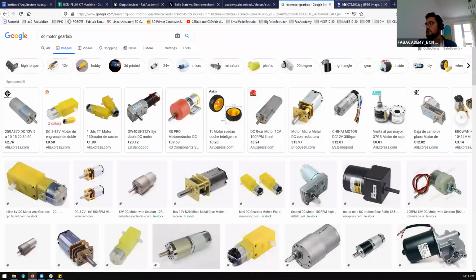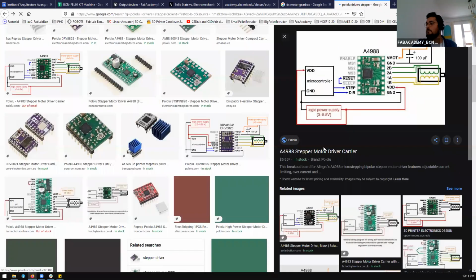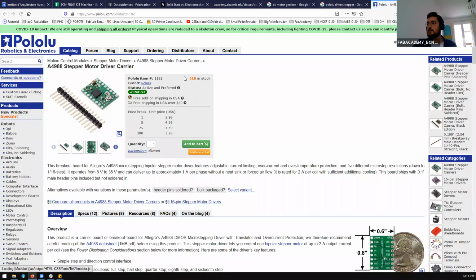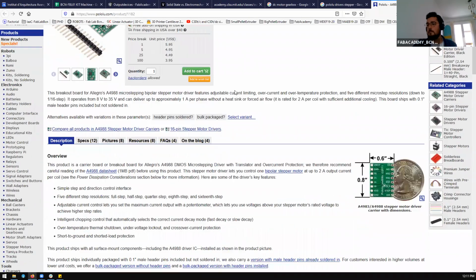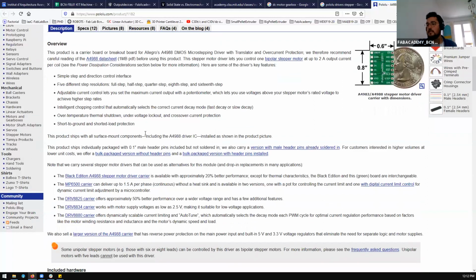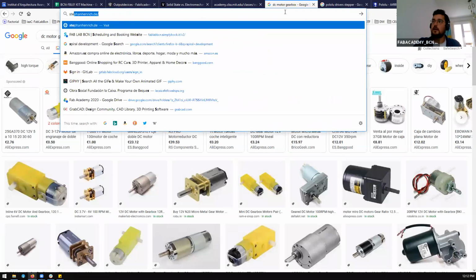How to choose these small guys? Based on the amount of power that you want to dissipate. There are many more things, because right now they are getting smarter and smarter, and you can control them. But what you always need to know is the maximum amperage that this can drive. So actually, it can only drive 1.5 amps. So one of the first things when you design a circuit is the stepper.